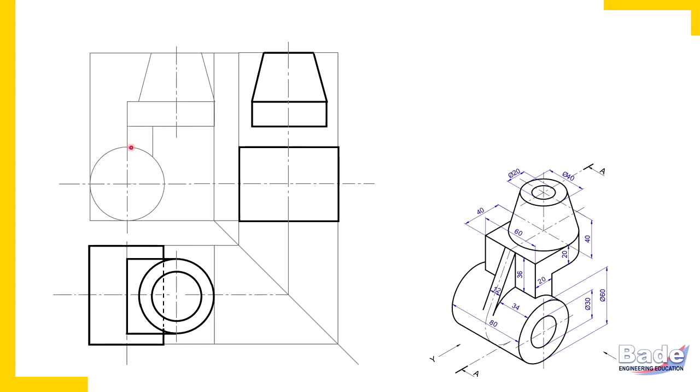This is the front view of that vertical plate. This plate is vertical. So this is the front view of the vertical plate. So to draw its side view, we should draw end projectors in the side view, that is, transfer the height of the plate. And to draw it in the top view, draw end projectors. Let's complete the top view first. So draw end projectors from that plate and complete that rectangle.